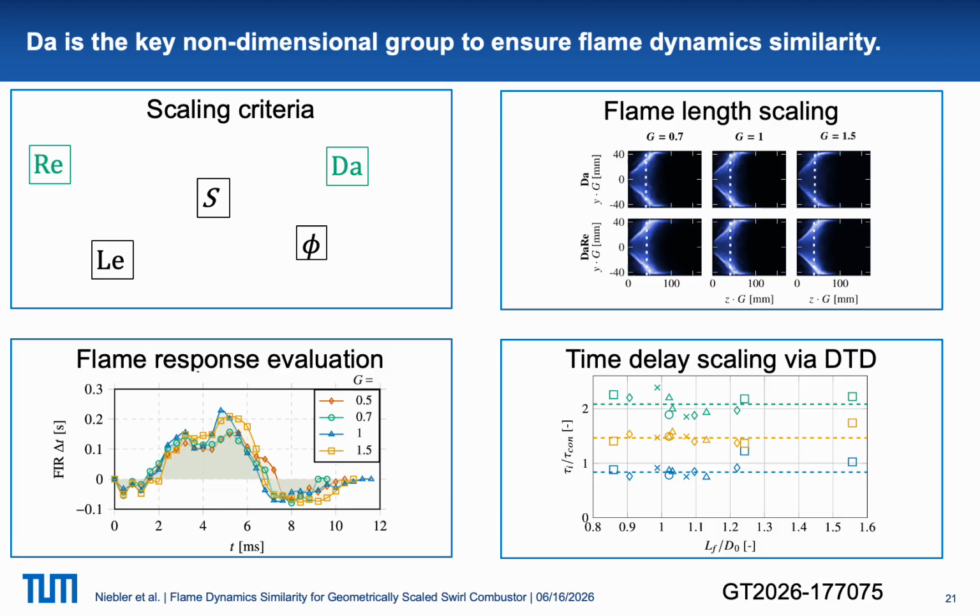What we want to use this tool for is to incorporate knowledge, for example, about the influence of the swirler position, maybe as well of the confinement, and also of different fuels and operating conditions, to, in the end, build a big parametric tool where we use input parameters like the equivalence ratio, or the swirler position on the geometrical side, and also on the operating condition side as inputs, and then have the flame response as a predictive measurement as the output of our model.